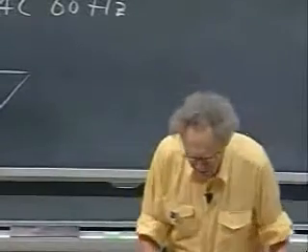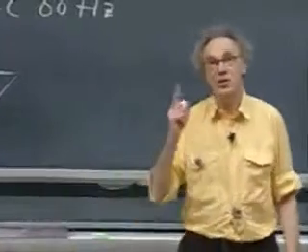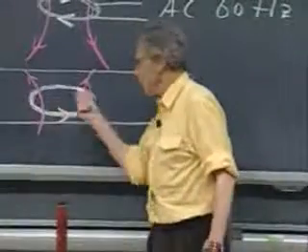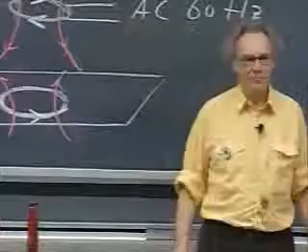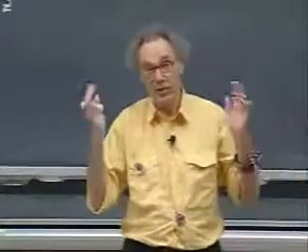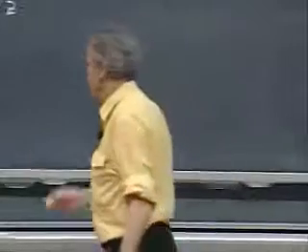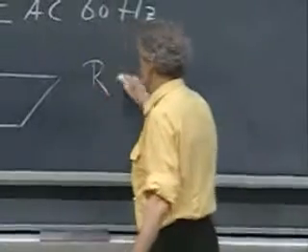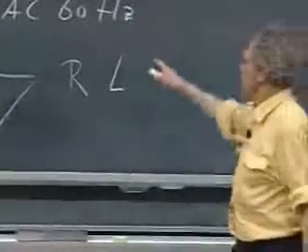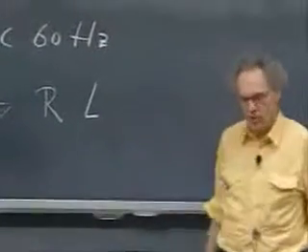And the secret lies in the self-inductance. This current that runs here runs over a path, which is very difficult for me to anticipate, which has a certain resistance R, and a certain self-inductance L. We know what omega is. That's about 360.